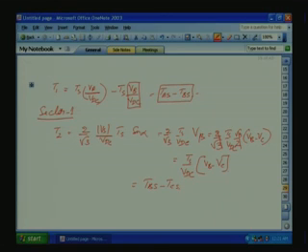So, if you know the sampled reference phase amplitude in sector 1, at any position in sector 1, T1 is equal to Ts into Va by Vdc minus Ts into Vb by Vdc, or equal to Tas minus Tbs, and T2 is equal to Vb minus Vc multiplied by Ts by Vdc, or Tbs minus Tcs. So this is very simple, easily you can find out. In digital implementation, this is very fast.